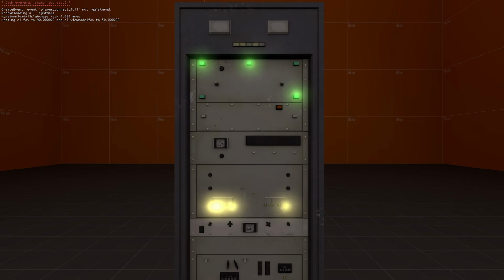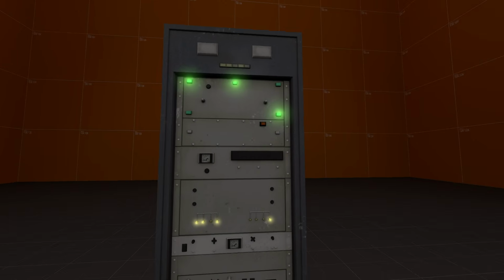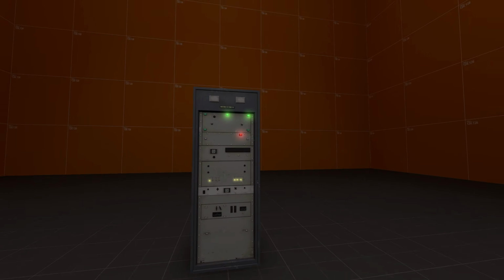Now you can tweak the settings if you like. Here I feel my yellow sprites are too big, so I switch to a scale of 0.05. I also recenter a few of them, and the result now looks like this.